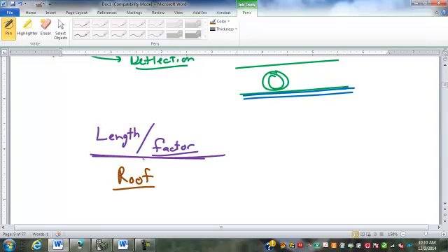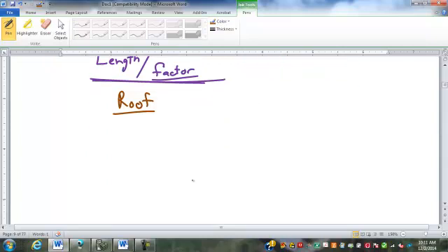You can see the plaster ceiling there bumps it up to an L/360, so it limits your deflection a little bit more when you have the plaster ceiling. Floors are always usually pretty limited, and especially, like I said, the textbook doesn't talk about tiles, but if you're going to tiles, it'd be L over 480. So how does that work?